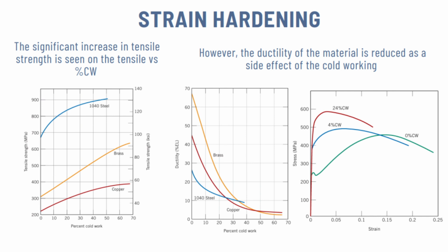materials. Additionally, the graph on the far right shows the stress versus strain graph of a material, which is carbon steel, with varying cold work percentages done on it. Notice the significant linear proportionality between the 0% cold work carbon steel and the 4% and the 24% cold work carbon steel, showing that cold working can greatly affect the yield strength of a material.